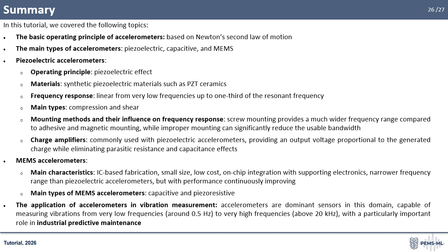Next, we focused on piezoelectric accelerometers. We explained their operation based on the piezoelectric effect, the use of synthetic materials such as PZT ceramics for their fabrication, as well as their frequency response, which is linear from very low frequencies up to about 1/3 of the resonant frequency. We also discussed the main types, compression and shear, and emphasized the importance of proper mounting.